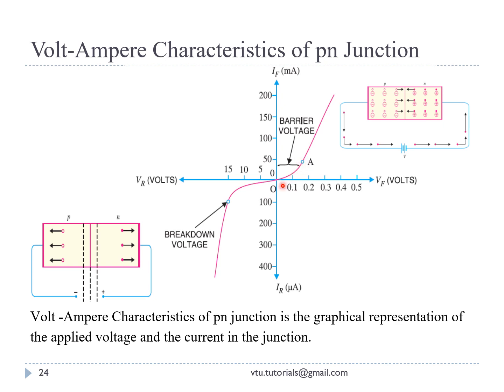Therefore, the current rises very sharply with increase in external voltage. This curve, A to the point over here, if you assume it may be a point B, from A to B is going to be linearly increasing. Hence, the forward current through the PN junction is due to the majority charge carriers produced by the impurity. So this is the forward characteristics curve of the PN junction.